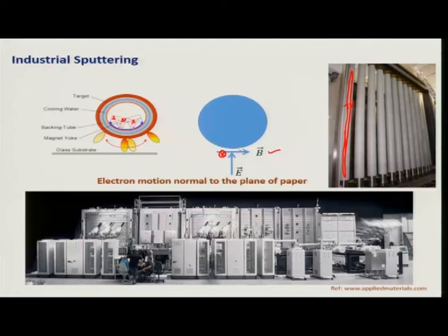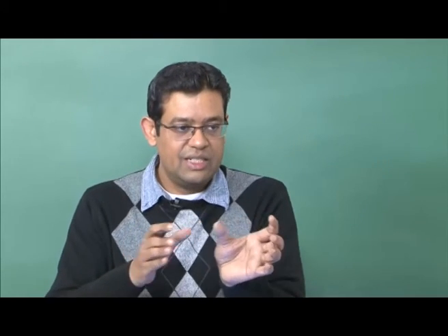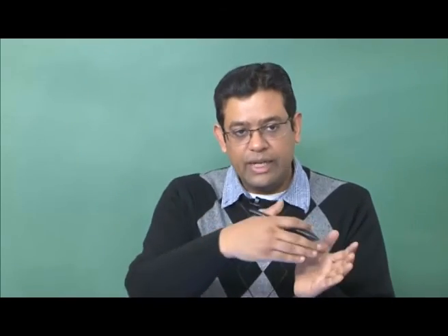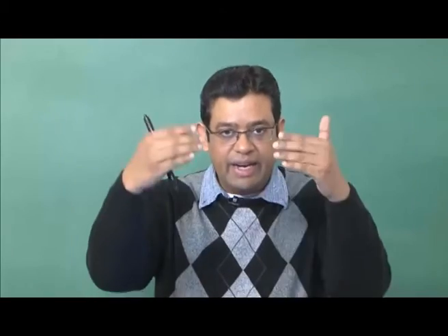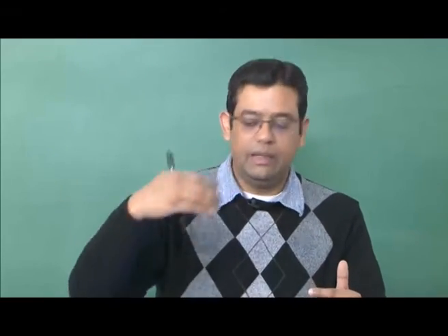In this geometry, because there are some gaps, to have a more uniform deposition, you can change the direction of the magnet. So, you can have the magnet pointing straight, slightly to the left or to the right, so that you can cover the entire area and deposit uniformly in front of that particular cathode.